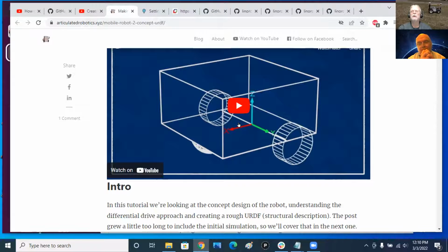And that would be under a Gazebo tag, and you say, I want to add a ROS controller, and you give the name of it. And typically you would say it's something like libros_control differential drive .so, something like that. You add that code in, and then a couple of lines under that, you have to put parameters. So you say, I want the left side to talk to whatever the joint name is for the left wheel. And another line says, I want to have the right side talk to whatever the joint name is for the right wheel.